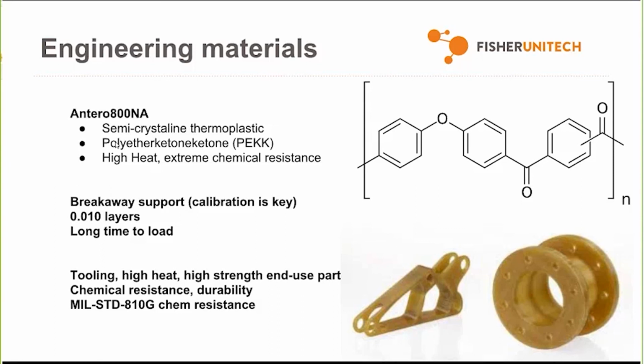Just like with Ultem, your calibration is key to being able to remove support material. Unlike Ultem, this support material is actually quite easy to remove after the part has cooled. So that'll save you a little bit of time and frustration trying to remove supports with gloves on. Just like Ultem, it does need to be printed hot, so it will take quite a while to load.